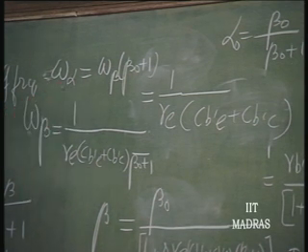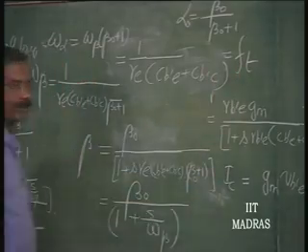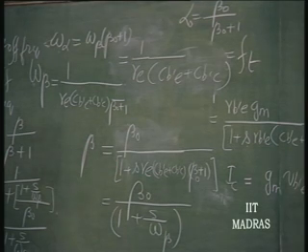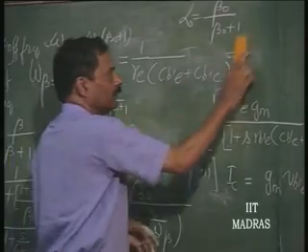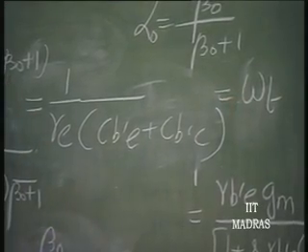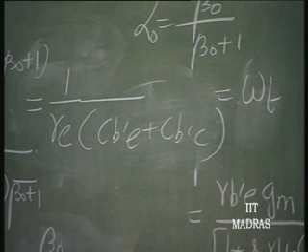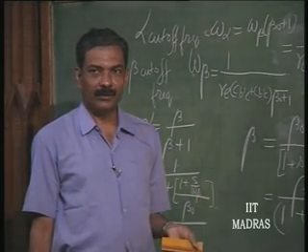So, this is also called Ft, the transition frequency. Ft is very nearly equal to, sorry, omega t, we will call this dimensionally omega t. Ft is omega t divided by 2 pi. So, this is called transition frequency. What is transit? The gain actually after this frequency becomes less than 1.